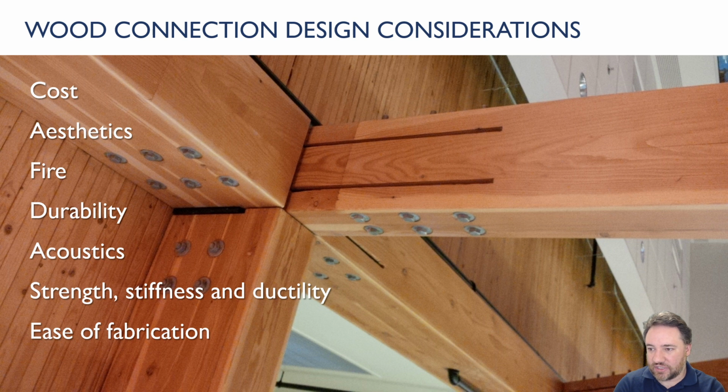In fact, for heavy timber connections like ones that you see here, sometimes the entire strength of the member is often governed by the connection instead of the strength of the member itself. There are a lot of things that we would want to consider, of course, when we're talking about wood connections. Cost is probably one of the most important, if not the most important, in a lot of cases, but also aesthetics are very important. You can see in this figure here, these are kind of concealed types of connections where plates are slotted into wood members, so you don't really see the big steel plates that are connecting these together.